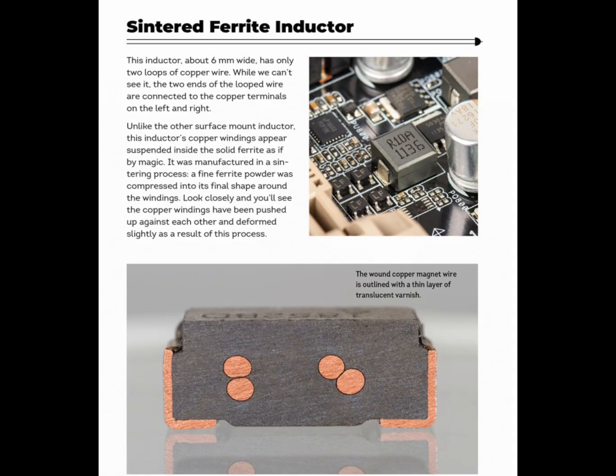Available in various configurations including toroidal, rectangular, and cylindrical shapes. The magnetic properties of ferrite allow for high inductance with low losses, making them suitable for high-frequency applications. Sintered ferrite inductors can achieve high inductance values in smaller packages, which is beneficial for space-constrained designs. They typically have good thermal characteristics, maintaining performance over a wide range of temperature.